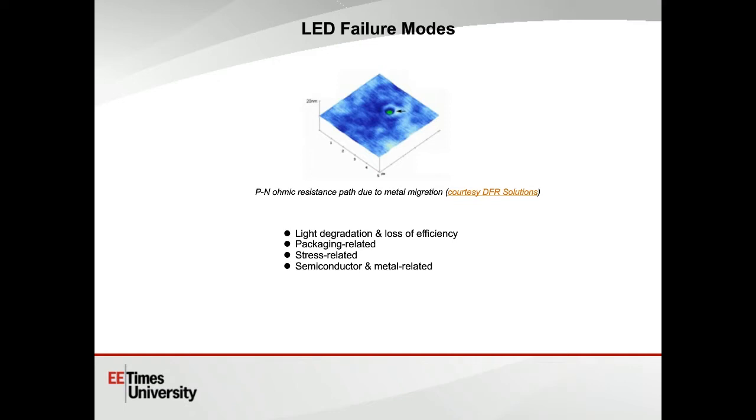Also, there are a number of failures related to the semiconductor operation itself, such things as dislocations due to crystal defects, concepts such as electromigration, metal diffusion caused by metal whiskers, which form on the die when it undergoes stress or high currents, effects due to such things as ionizing radiation and so on. These are all very specialized things that we won't really discuss here, but you can go to any of the semiconductor company sites and see discussions in the quality and reliability section about failure mechanisms such as this. I would encourage you to take a look at those if you're interested.